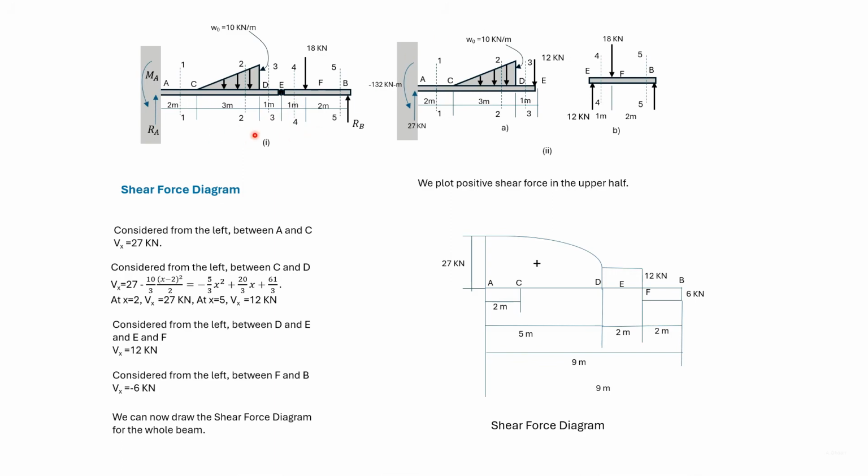So in this case, there are 3 unknowns: the reaction at B, the reaction at A, and the moment at A. There are also 3 equations, the 2 equations from statics and the additional equation that the bending moment at the hinge at E is 0. Hence, we can solve for the 3 unknowns.